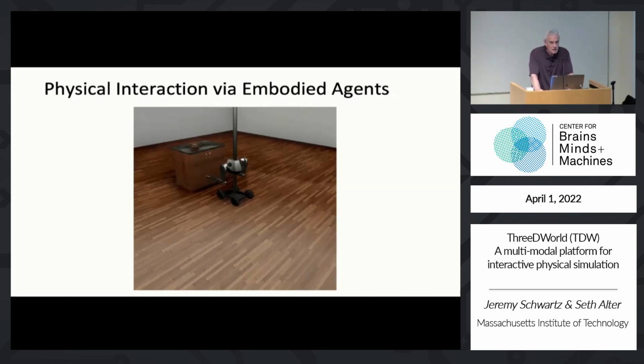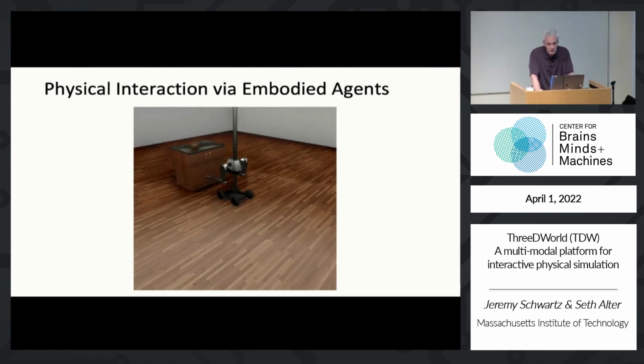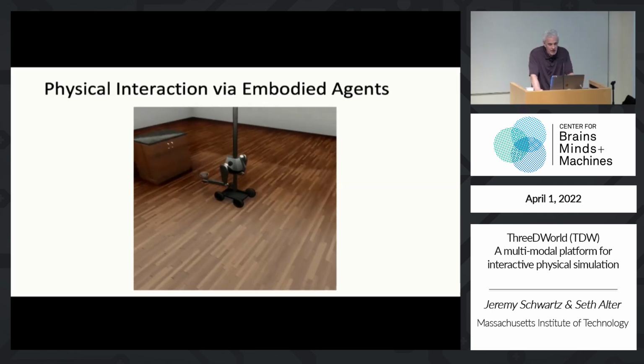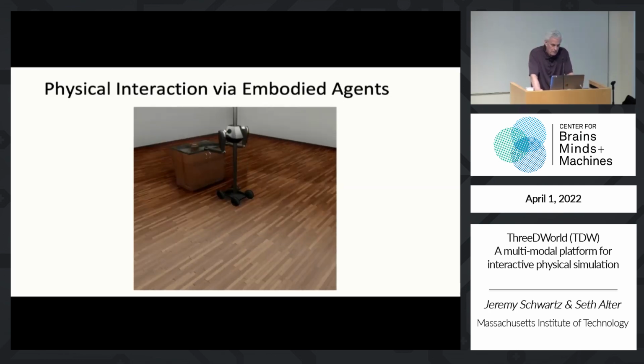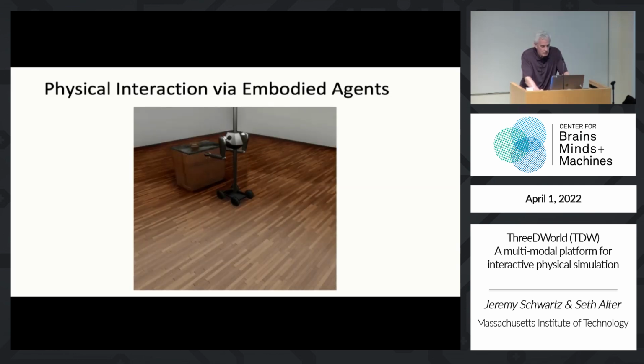Magnabot is fully physics-driven. There's no animation involved. Directional movement and turning are achieved by controlling revolute joint drives. Arm articulation utilizes 1 degree of freedom or 3 degree of freedom joints in combination with an IK or inverse kinematics system to facilitate sophisticated reaching actions. As you can see, Magnabot can also move its torso vertically along its central column, implemented as a prismatic joint, allowing it to reach objects at a considerable height above the ground.